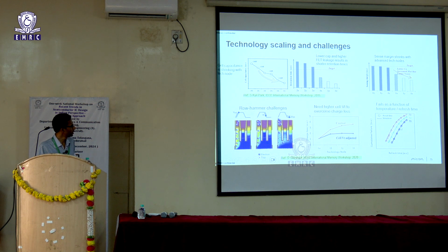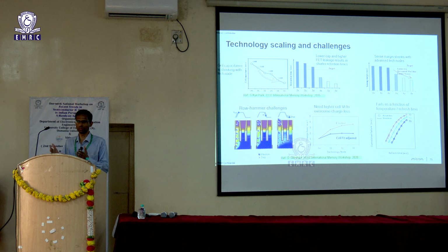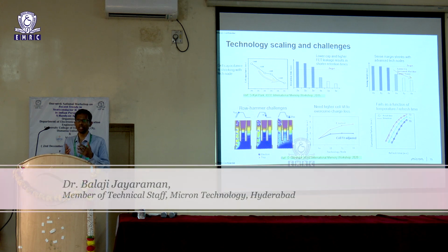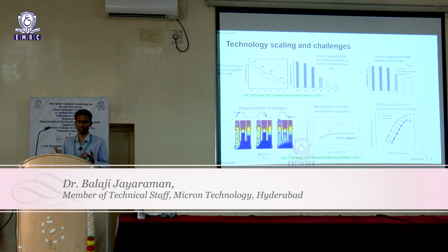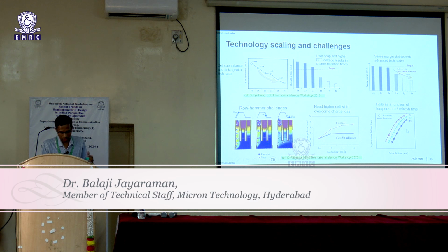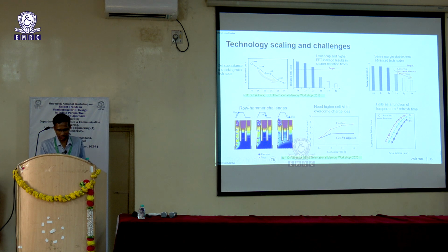And then we talked about retention times. The retention time as a function of temperature as well. So if you are doing a room temperature operation versus a high temperature operation, your refresh rates have to be much higher at higher temperature. So that again is a challenge, and once the cell is getting scaled, it's even more challenging.